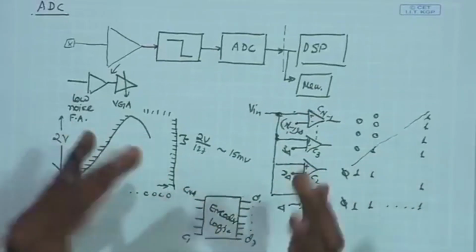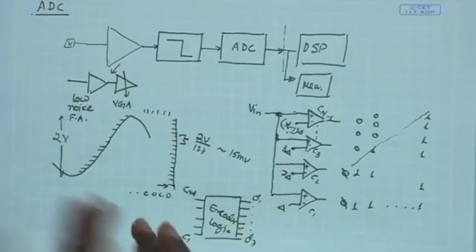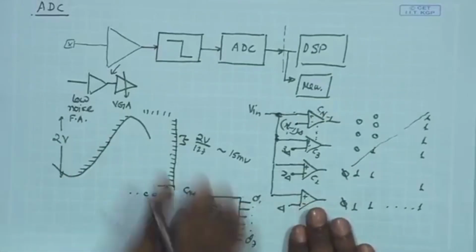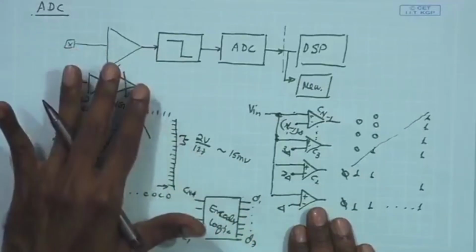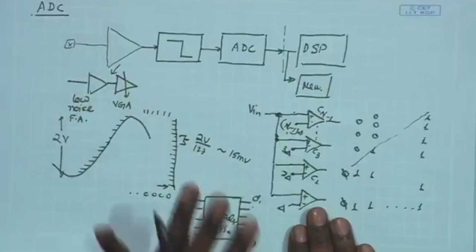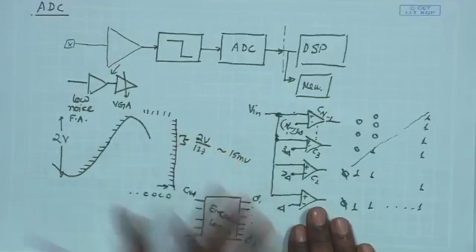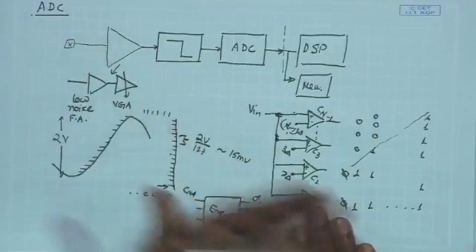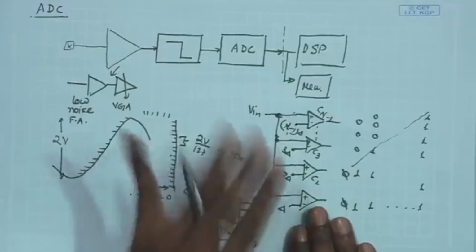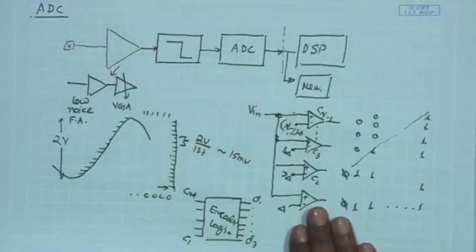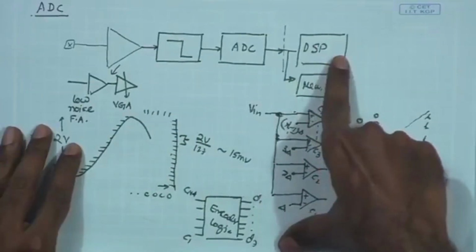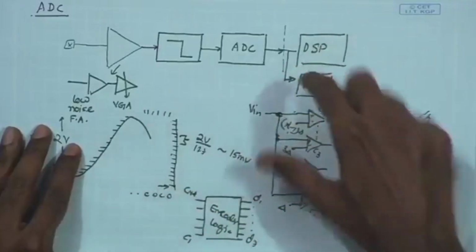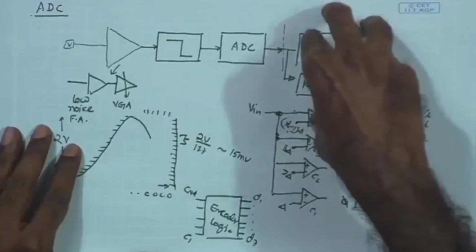So here in our case, we are looking at a biomedical signal which is a relatively low frequency signal, and also an application having moderate resolution. We may be able to do the required processing with just 7 bit of resolution, that is moderate or relatively low resolution. You can have applications where just 4 bit may be sufficient. In this application, we are looking at neural signal acquisition and processing. People have shown that 7 to 8 bit of precision may be good enough for extracting the required information in the digital domain. So the target of the ADC resolution comes from the data processing requirement.